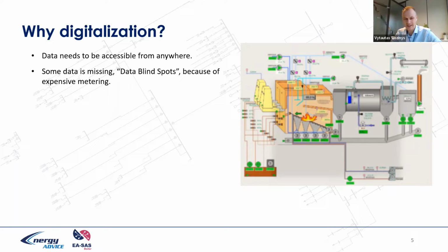Probably we can add a flow meter, for example an air flow meter or flue gas flow meter, but finally these flow meters would have metering error, would be expensive, and probably create more problems than value.